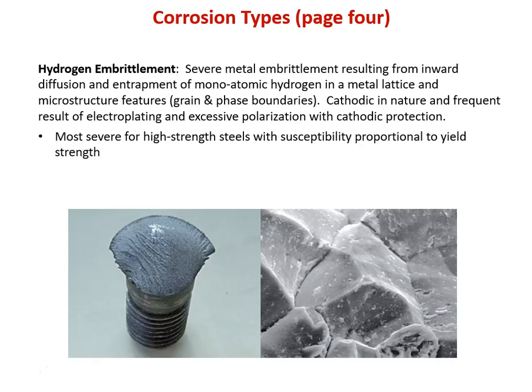Hydrogen is a tiny, zippy little species, and it can get into crystal lattices, and it can prevent dislocation movement, just like we discussed in our defects section, and this causes a material to become very brittle. This is particularly problematic because we can encourage this to happen by applying cathodic currents, which we otherwise do to prevent corrosion. This is one of the means of corrosion prevention that we'll get to.